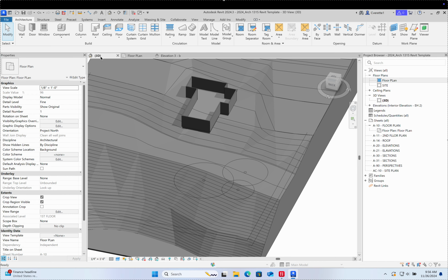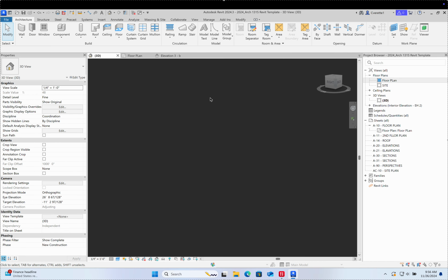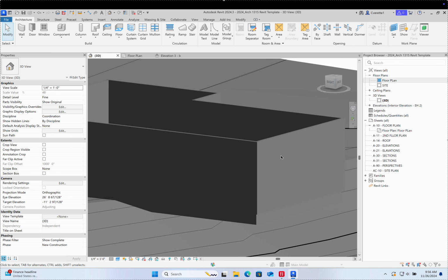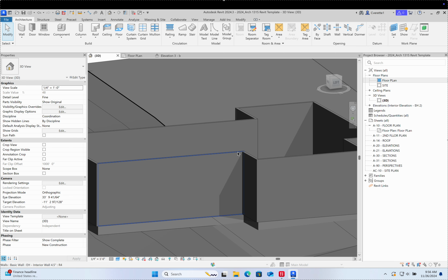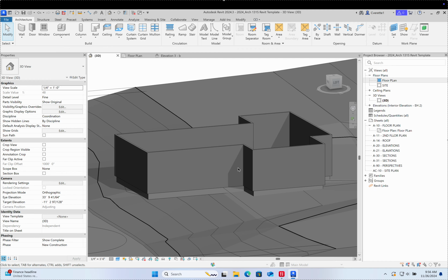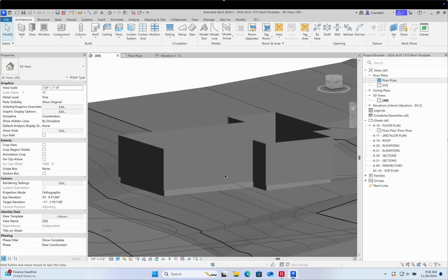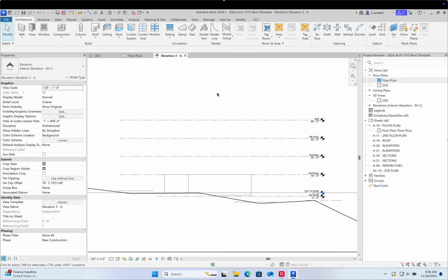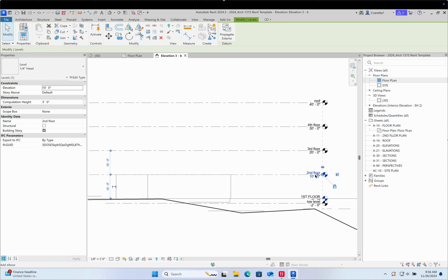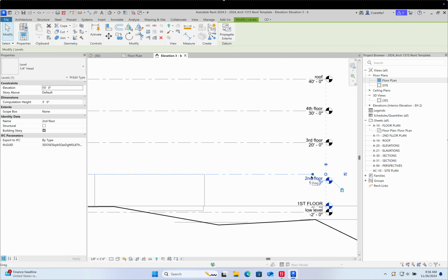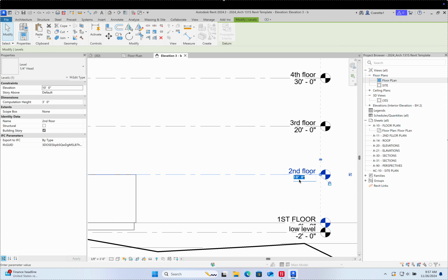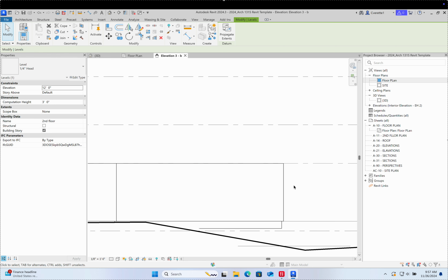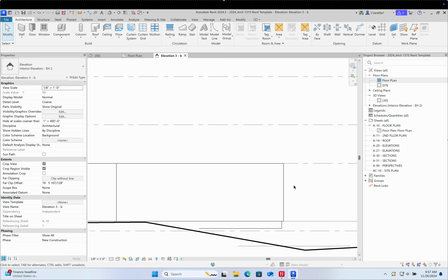Again, there's something nice about Revit, I'm not going to lie to you. Right? To be fair, that would take a little bit longer in Rhinoceros. However, changing it is a different story, right? But that's looking fair. You know, it's going up to level 2. You know, what if I decide that level 2 is a little bit taller? Oh, actually, you know, I think I want 12 feet, so I'm going to type in 12 feet. And it's going to automatically change all of those walls because of the parametric nature of them being connected.